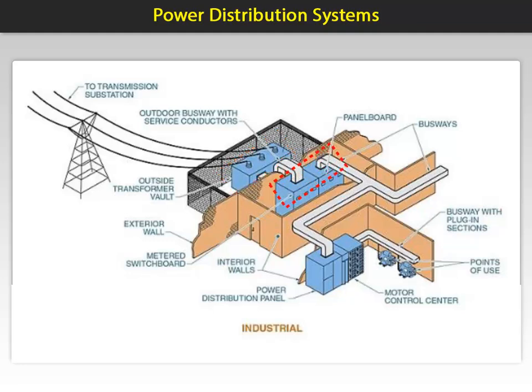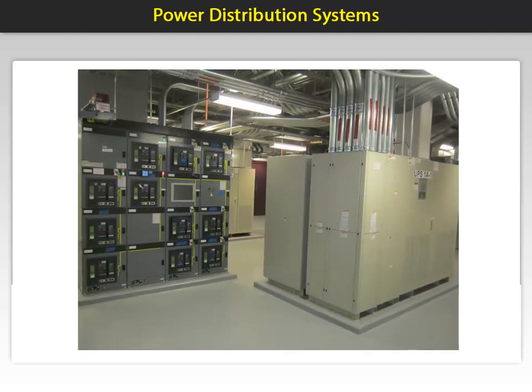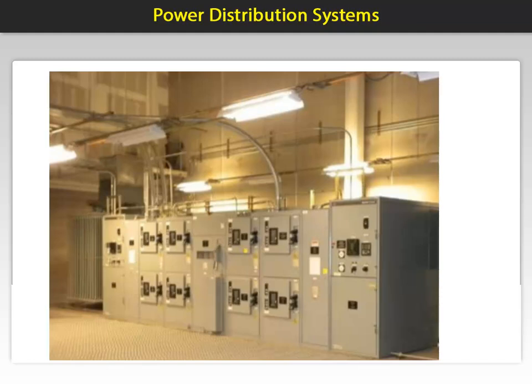Depending on the size of the plant, there could be one or more indoor power centers. Here is an image of a typical indoor power center. You will notice that cable and conduits instead of busway helps to distribute power. Power centers may also be double-ended as seen here. These accept two different feeds and have a tie breaker that allows for supply power flow to feeders in the event one source goes down. These are also referred to using the term main tie main.